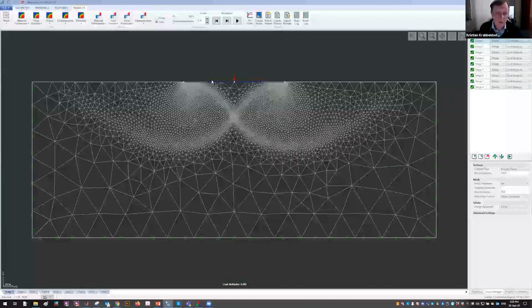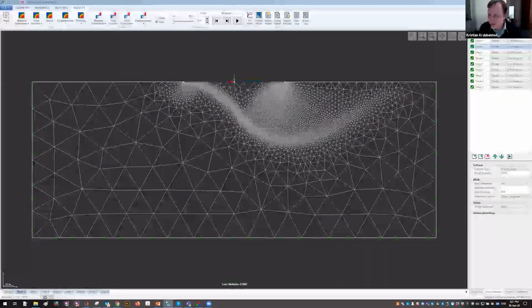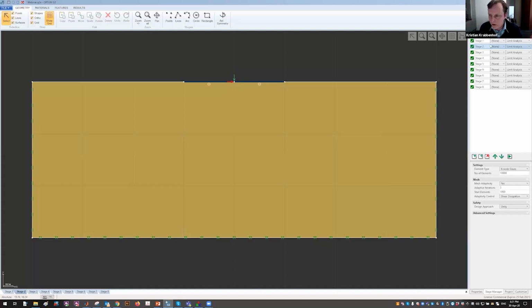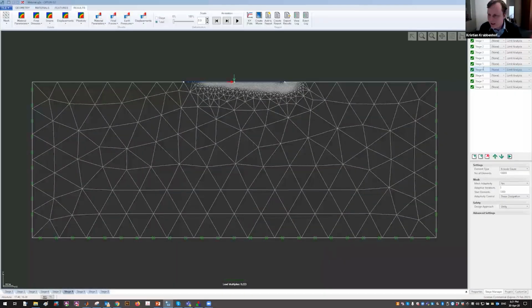Then I go here right to left, so I apply a fixed vertical load, somewhat less than my maximum load, and then determine the maximum horizontal force. And I then can see how the failure mechanisms change as the load inclination increases, and I'm getting now down close to the origin where things are dominated by sliding.